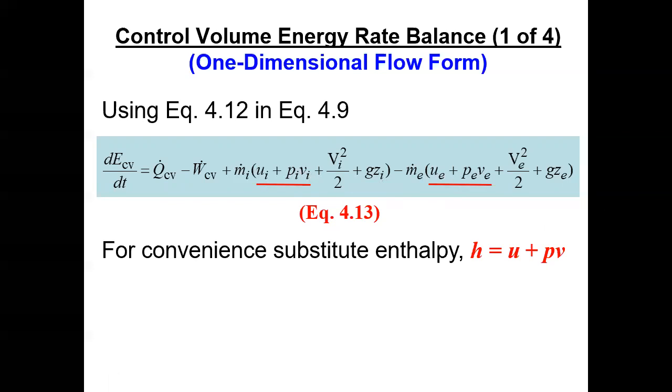Now, enthalpy. Now you see why enthalpy is really defined. Because if you didn't have enthalpy defined, you'd have all these little P sub I, specific volume sub I, and P sub E, specific volume sub E, running around in all of your equations. And some smart engineer back in the day said, hey, these are all properties. Why don't we just combine this internal energy with pressure times specific volume and call it something and tabulate it, and it'll make all our calculations a lot easier. And that's what they did. They called it enthalpy. And so enthalpy is the internal energy plus flow work.